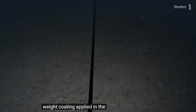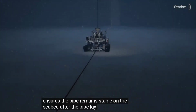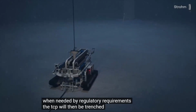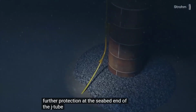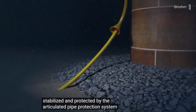Weight coating applied in the factory ensures the pipe remains stable on the seabed after the pipe lay. When needed by regulatory requirements, the TCP will then be trenched for further protection. At the seabed end of the J-tube, the exposed part will be stabilized and protected by the articulated pipe protection system.